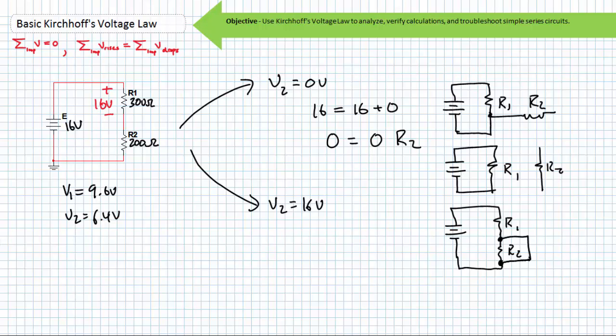Improper placement on a protoboard is the number one error I've observed in a lab environment. Actually, this is the number 2 error, because the first error is wearing a baseball hat sideways. A resistor with both terminals placed into a single node that is electrically connected via a 0 ohm conductive clip, not visible to the naked eye, but easily recognizable to those that know how to use an ohm meter in a protoboard, presents no resistance from terminal to terminal. This resistor is shorted out via the conductive clip.